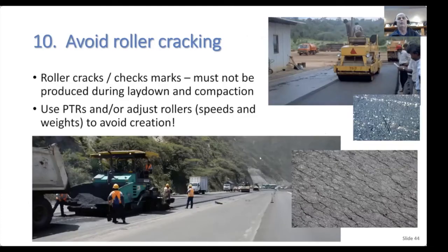Finally, I'll come on and I'll mention this one. This is the roller cracking aspect. Really, you must always make sure that you avoid roller cracks when you construct pavements. A couple of pavements here. One of these is in Sri Lanka, one of these is in South America. But you know, when you construct the pavements, this was a paving trial we were doing, and we had to modify rolling patterns until we made sure that we could successfully pave without getting any cracking.